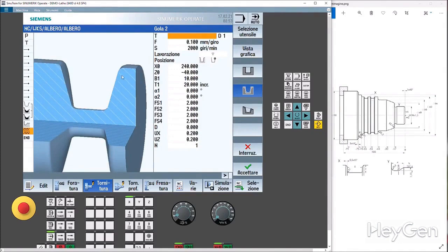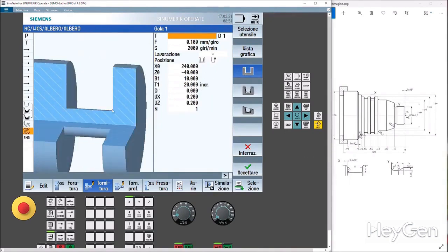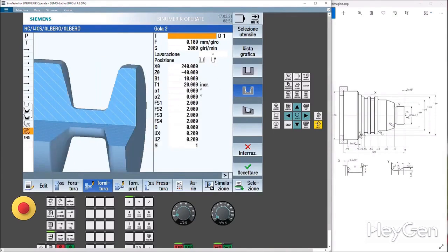So this is misleading because you say, no, I don't have a trapezoidal groove. No, it's true that you don't have a trapezoidal groove, but you do have some chamfers here at the entrance and groove bottom radii R1. Okay? If you use this, you can't put the radii at the bottom of the groove. So use this, and our angle will simply be a 0 angle.